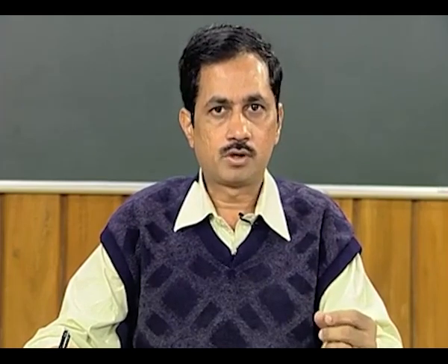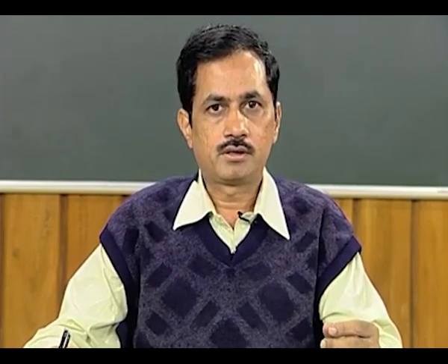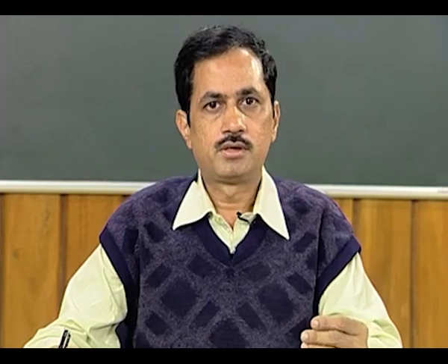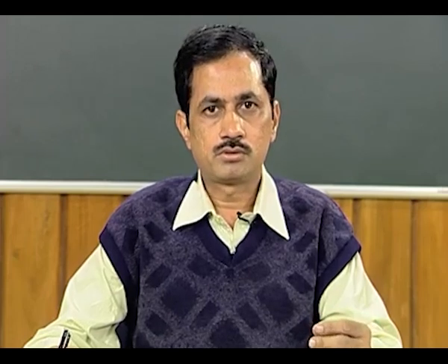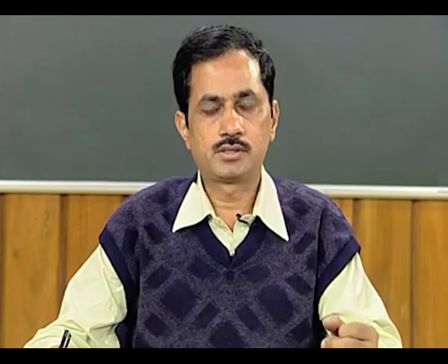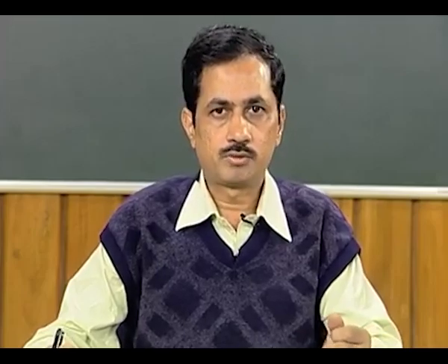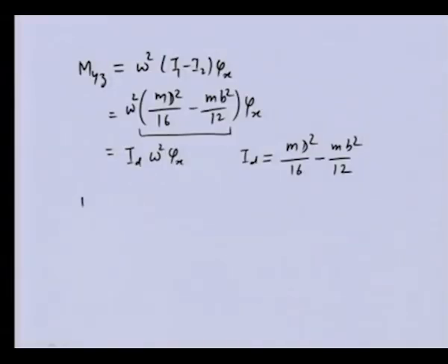But now once we obtain the gyroscopic moment, if we consider the translatory motion also, then as for the thin disk case we will have the gyroscopic force Fy as m omega square into y; in this particular case, sorry, this will be delta. Delta is the linear or translatory motion of the long stick.